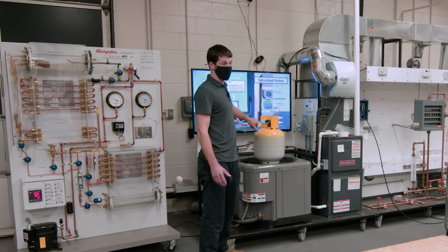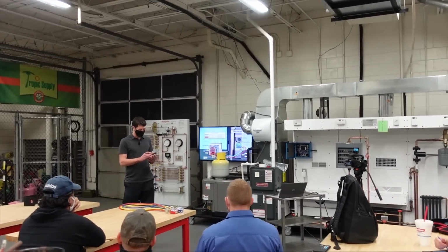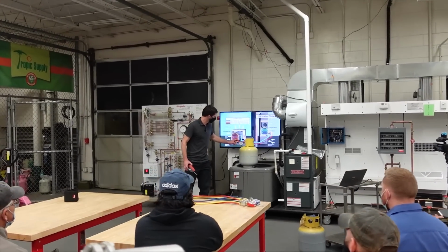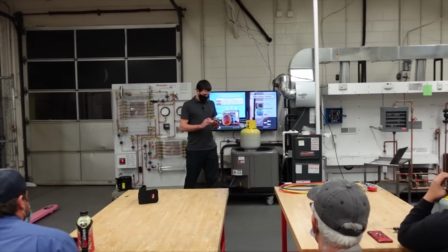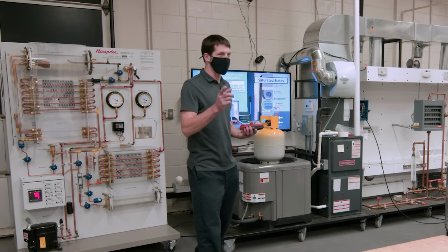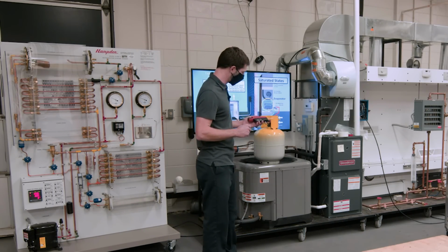And you see it reads about 78 degrees. Now, this is higher than the temperature in the room right now. So there's actually a little bit of air in there. It's either that or this compound gauge was not calibrated on 0 before we connected it. That was my responsibility, so it's likely that it wasn't. No, I think I opened the handle before checking, but I'm pretty sure they were at 0.